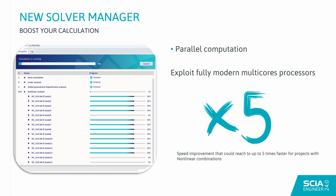As you can see by the screenshot that I have here on the left, multiple nonlinear calculations are running at the same time on the same machine, and this will change your calculation. We even saw big projects that used to take hours to calculate, and sometimes we really needed to split the projects because we had more than 400 nonlinear combinations. This is no longer the case. We can run the same project on the same machine in really 10 minutes, winning enormous time.